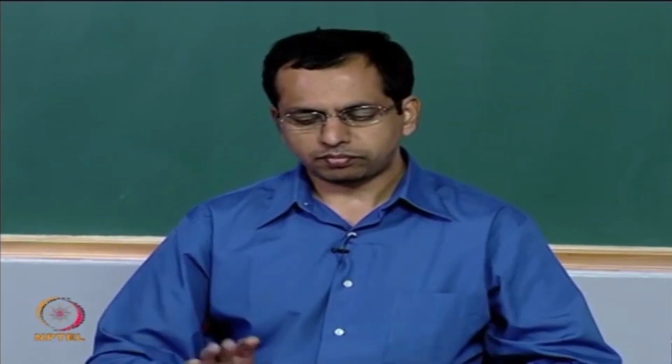Okay. So, this is what we can conclude from the Nyquist plot, and so far we have not done much new. We have introduced the Nyquist plot and we have evaluated the same things that we evaluated earlier, that is we evaluated instability for 2 extra poles, 3 extra poles, 1 extra pole and so on, and the same thing we verified with the Nyquist plot. What this has helped us is to show that what you get from the Nyquist plot is consistent with what you got earlier, which is the exact analysis. At the very end, we did a small generalization to multiple poles which are not at the same frequency, but